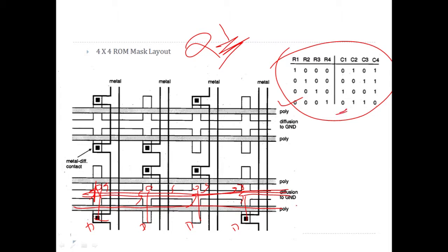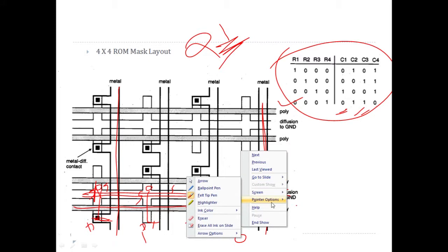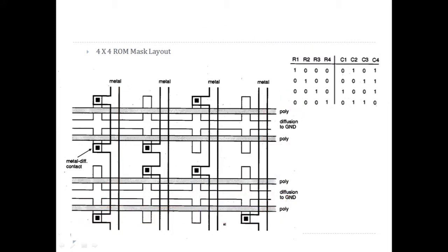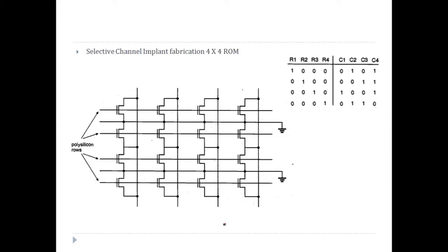And here first we need to store 0, so that means the drain should be connected to the bit line. So there is a metal bit line over here where the drain is connected. Here it is open, here it is open, because 0, 1, 1. So whenever you want to store 1, you keep it open. Whenever you want to store 0, connect the drain to the metal line. So like it is shown here. Okay, so it's very simple to draw. I hope you understood it, and you can draw it using color rules. You can follow the color convention for this using the lambda rules.